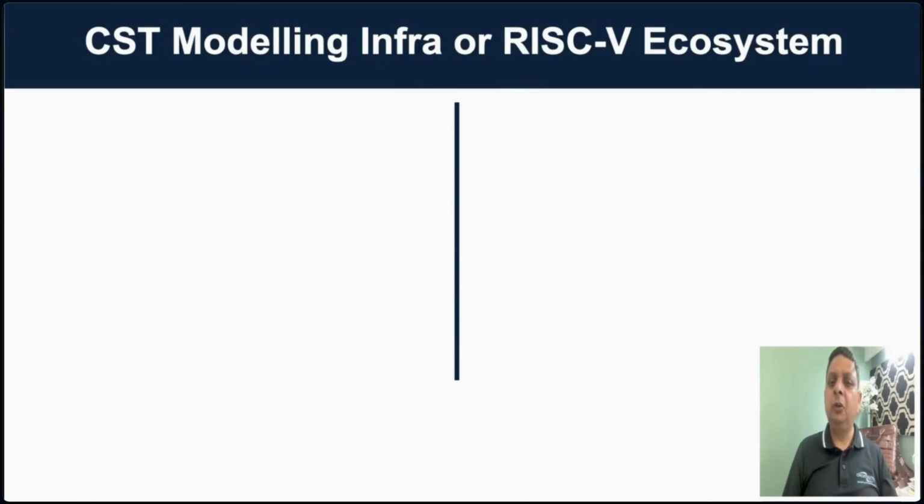We have a reference virtual platform of CORE-V MCU developed using CircuitSutra modeling methodology, which is based on standard SystemC TLM 2.0. It's mainly suitable for embedded software development and testing, and further extended for advanced flows that will be covered in the webinar today. This can be useful for companies involved in the development of RISC-V CPU, RISC-V based SoC, or IP for RISC-V based SoC. It enables them to effectively and quickly deploy higher abstraction shift left methodologies. We will be adding more components to this framework based on customers' requirements.